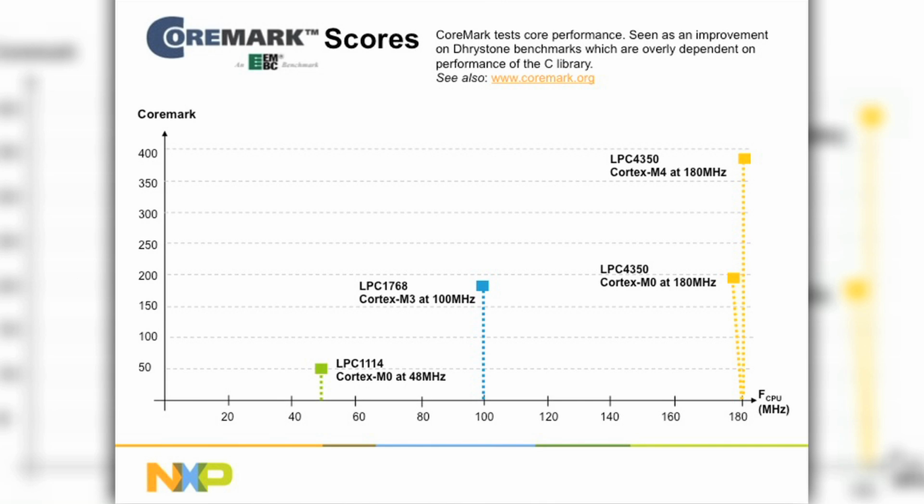And we see on the very left side is an 1100, an M0 that is running at 48 megahertz, and the score was 50-ish, 50 point something. And these are already posted on the website. If you look at the 1768, which is an M3 running at 100 megahertz, I think it was 175 in that range. Now, the M4 runs at 180 megahertz, and so it's almost, I think, 380-ish on the performance.